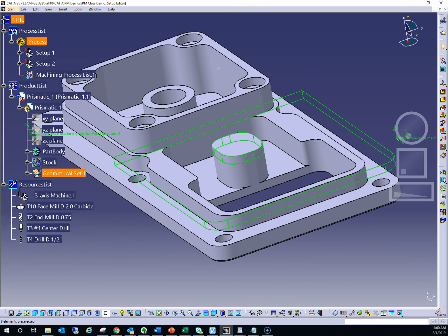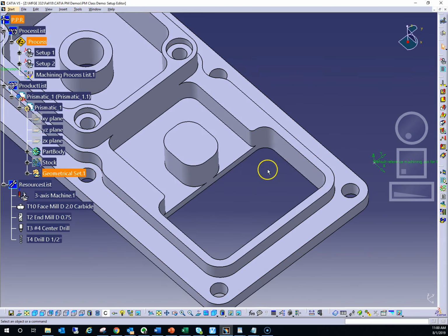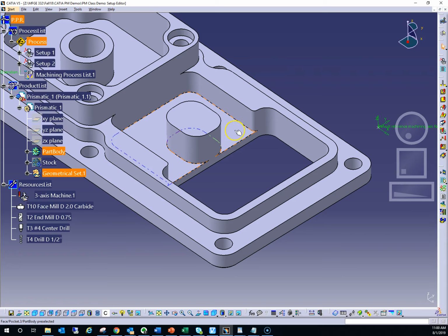And then after that pocket's removed, we can step further downwards into the pocket itself. Notice that this pocket has an open bottom. However, there is still part of the pocket that has a floor, so we need to consider that too. So we probably need to machine this using 2 pockets, just as we did for this part of the part